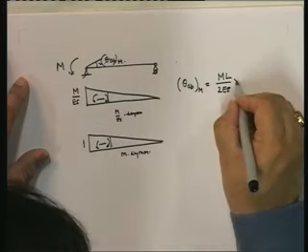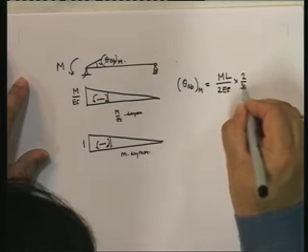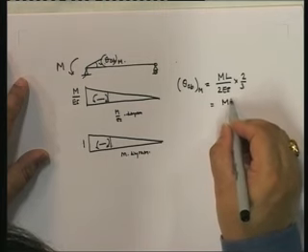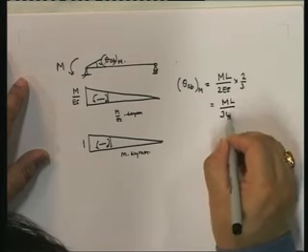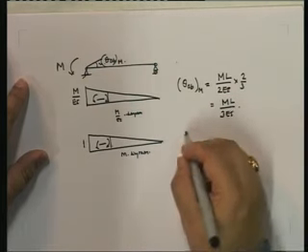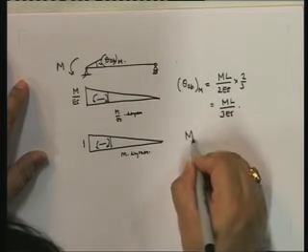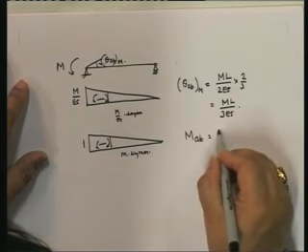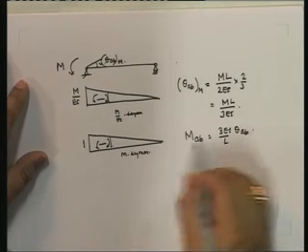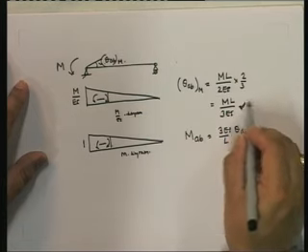At that value it is. And note, since this is hugging, this is the same direction, so it's positive. So it becomes equal to ML upon 3EI theta. Which, if you look at it, is actually the same. I mean, we could have found this out easily, because MAB is equal to 3EI upon L theta AB. We know this. And you will see that exactly the same relationship you get from here too.